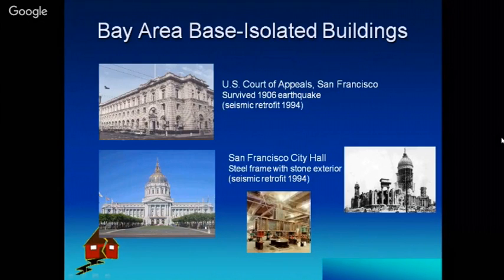and they have first supported the superstructure with some cantilever, vertical structural supporting. Then they have chopped off some part of the foundation, and then placed the bearings into the structure, connected the base isolation bearings structurally with the foundation and the superstructure, and then left the structure to vibrate in base isolation, so that the displacement is reduced corresponding to any earthquake.